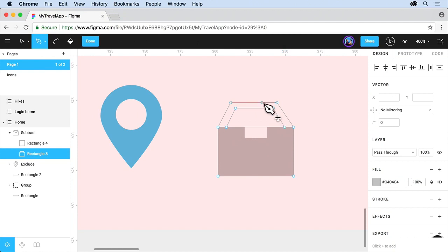There we go. Now once we're done here, we could, if we want to, come to an individual anchor point and drag it or move it or do all kinds of things. You can even reshape or bend paths using the bend tool. I don't really want to do that, but we can also tell it what to fill with a color. So if you come up here, you'll see that we have the paint bucket tool. Click on that. It's going to use the same fill that the rest of the shape had.